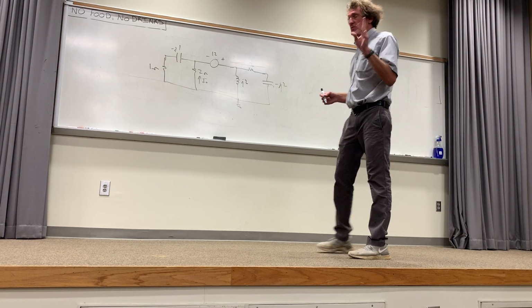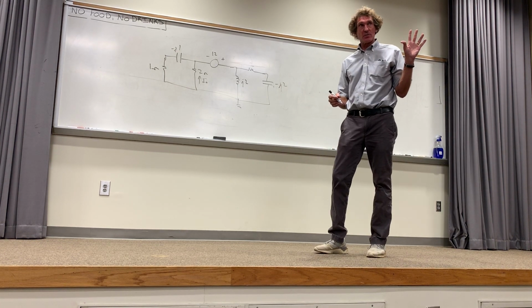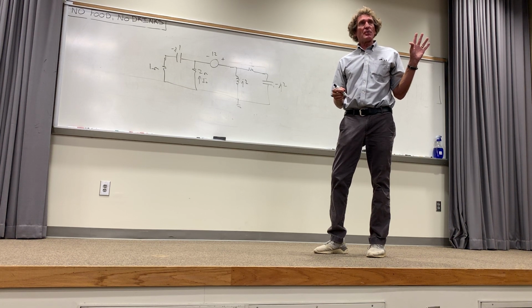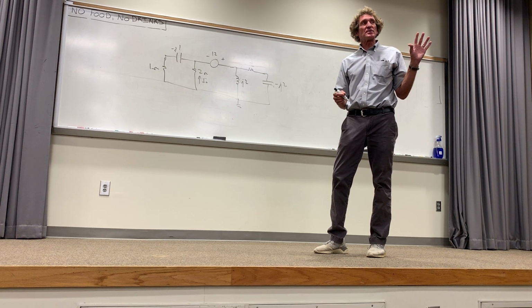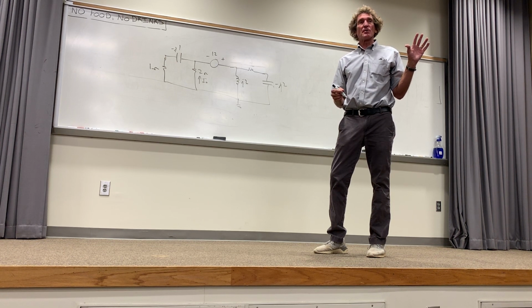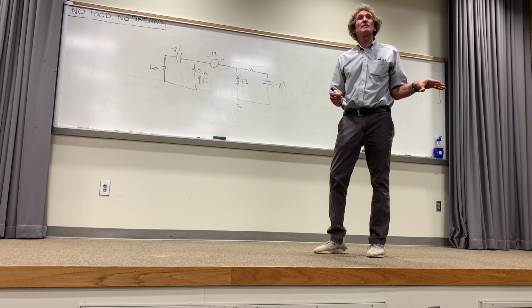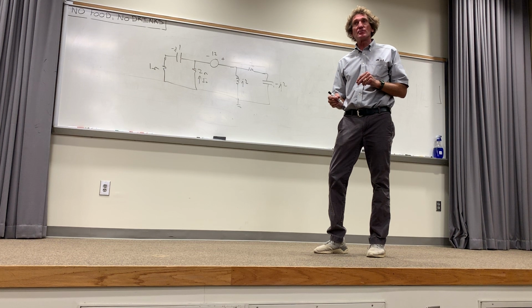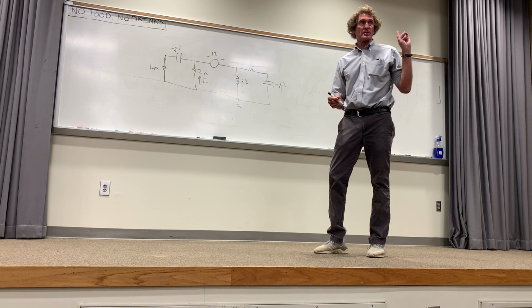Now let me just discuss 2 things you can do. I want you to notice this. You see how we have only one voltage source? Whenever you have one source, usually the problems can be done very efficiently by just combining impedances to get a net impedance across it, finding the current through that, and using current division or voltage division to find what you want. When you have only one voltage, it's very easy.